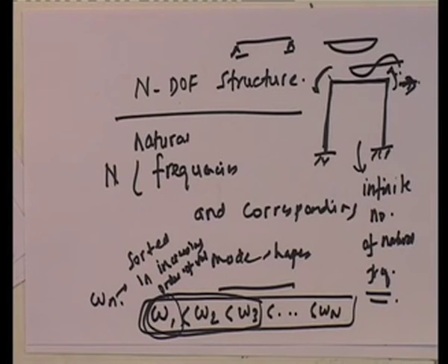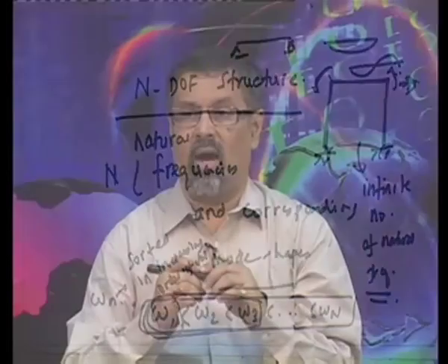Okay? So, I have completed my equations of motion, and I have introduced you that ultimately the free vibration problem is nothing but an eigenvalue problem, and we also saw that since M and K are positive definite symmetric matrices, the eigenvalues are all positive and distinct. Okay? We will continue with this free vibration problem in the next lecture. Thank you very much. Bye bye.